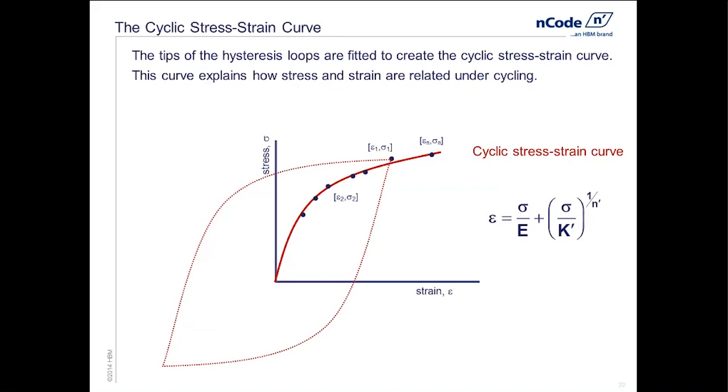If we're using the fatigue test to generate this curve, what we're actually going to have is a whole family of hysteresis curves, each one of these at a different strain level. And so at the lower strains, there's smaller hysteresis curves, and as we have higher strains, they become larger. And what we do is we pick the upper corner of the hysteresis curve, and that point is used as a stress-strain value on my stress-strain curve. So what you're looking at here, these blue dots, are basically this upper vertex of the hysteresis loop for different load levels.